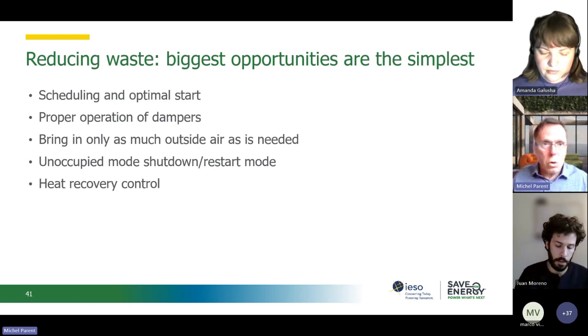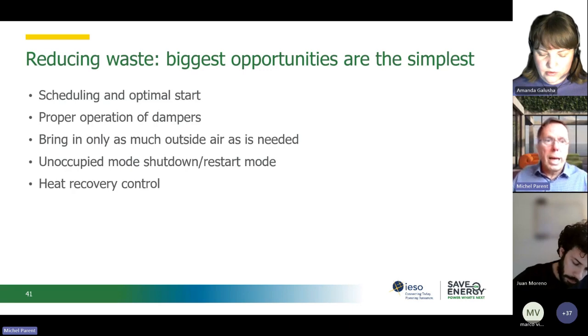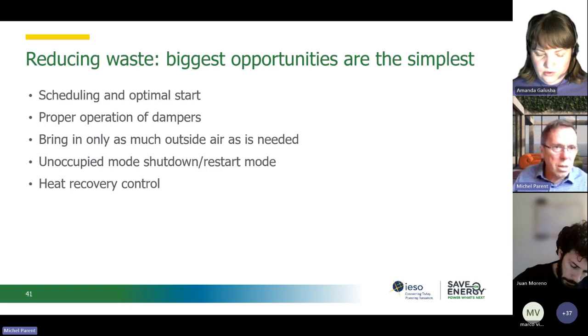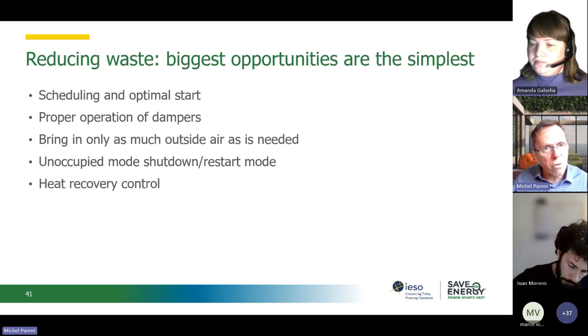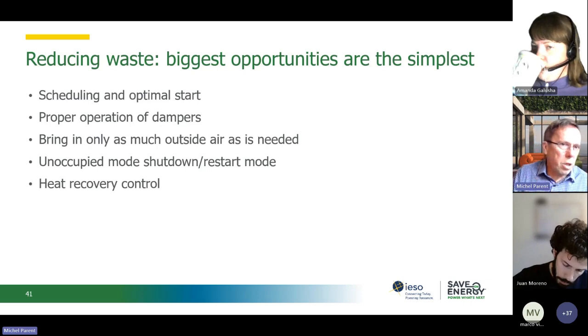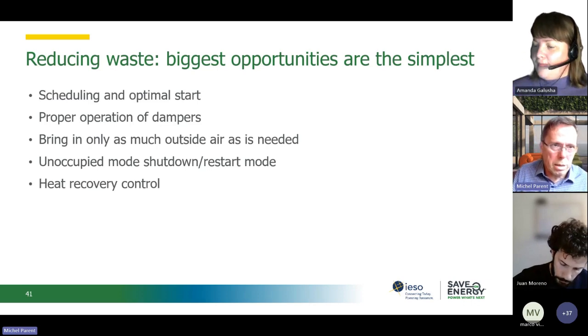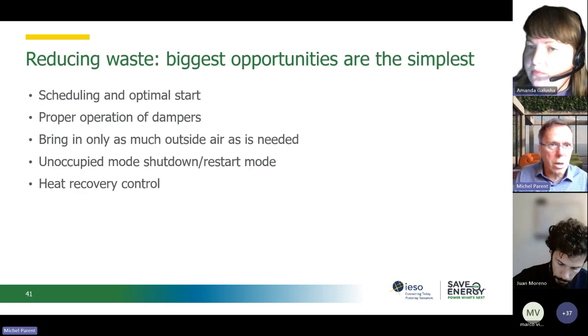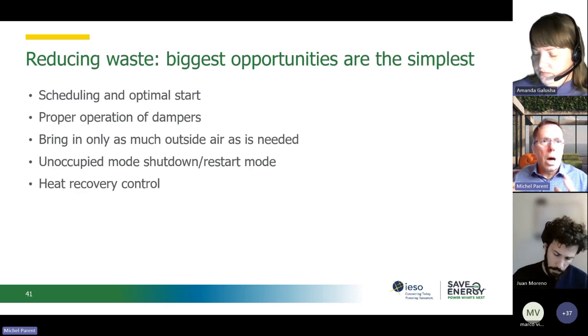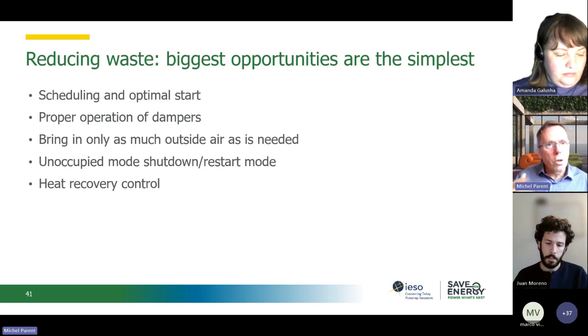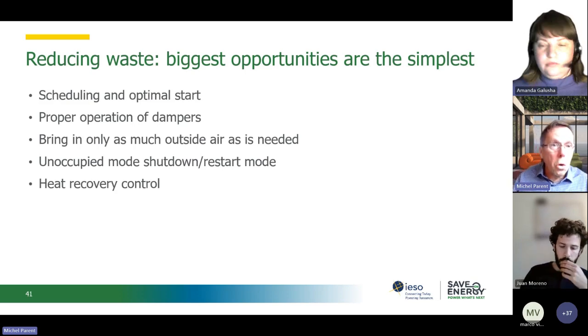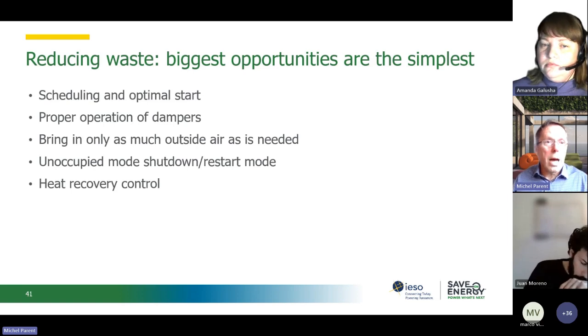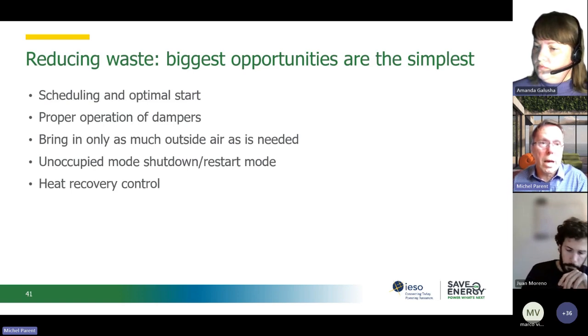So look at all your systems and ask yourself, is it running to meet the requirement? That means, do I understand what my HVAC system is supposed to do, what it's supposed to provide in terms of services? If it's only a ventilation system, such as a makeup air unit, I don't need to start it early. A VAV system, I mentioned, is a cold deck system. It's not a heating system. You don't typically need to start it early in the winter. So scheduling optimal start is one of those opportunities that will impact both your load and your equipment runtime. So you will hit, like I said, 2 of those saving mechanisms.